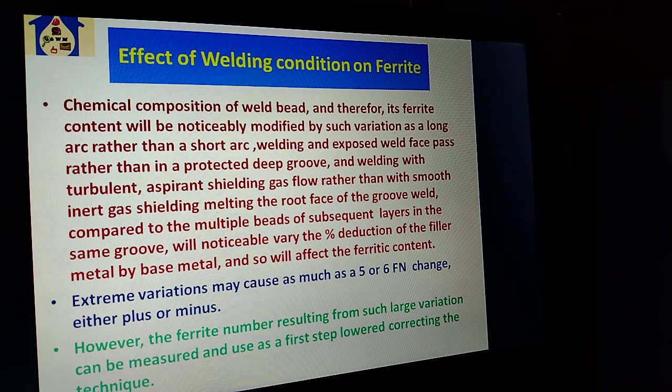Melting the root face of the groove weld, compared to the multiple beads of subsequent layers in the same groove, will noticeably vary the percentage dilution of the filler metal by base metal and so will affect the ferrite content. For example, variation may cause as much as 5 to 6 Fn change, either plus or minus.